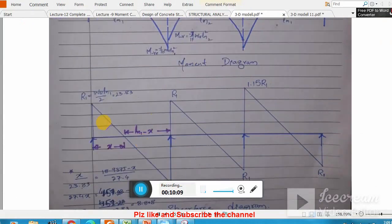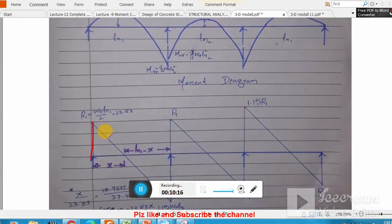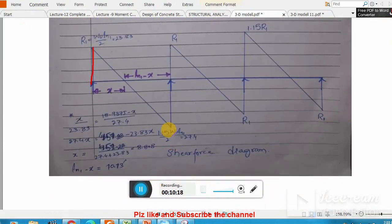Then the shear diagram: I will jump to R1, then due to that loading I have to go down, and due to that reaction I will jump, and then due to load I will again go down. Now the very important thing is that we need to find the distance where the shear becomes 0. So I assume that it is x. The next distance is L1 minus x.